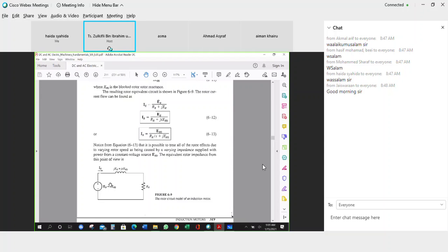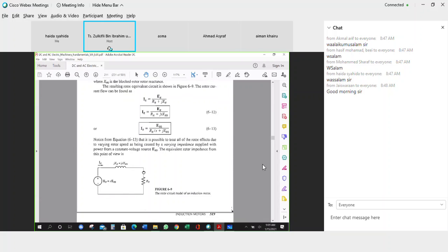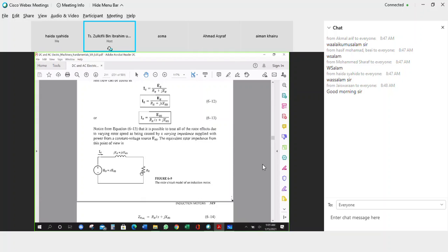So this one equals S E_R0, and also R. This one is just the rotor winding resistance. So the inclusion of S here represents slip, and this shows that when the machine is running, you can simplify the rotor circuit to something like this. Okay.